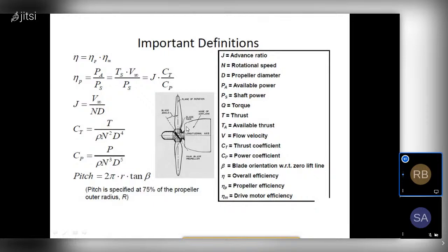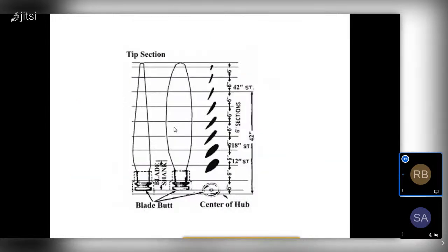And here we have the CT and CP are not affected by the design, but thrust and power are affected. Okay. So for an air propeller, the performance of a propeller and engine depends upon the altitude also. That is the density. So that's why we can say that propeller engines are preferred in low altitude and short range purposes.